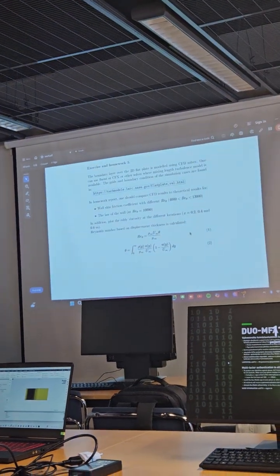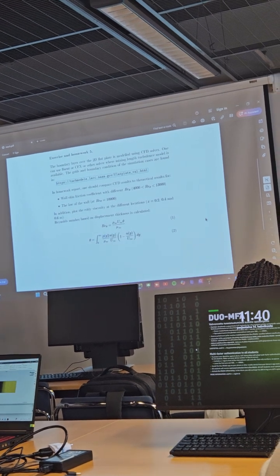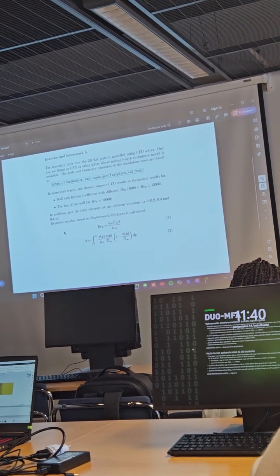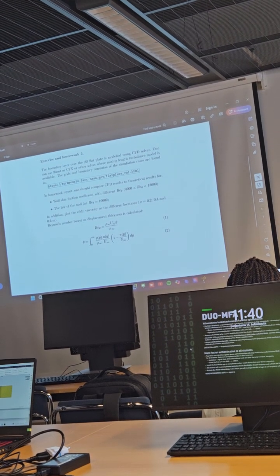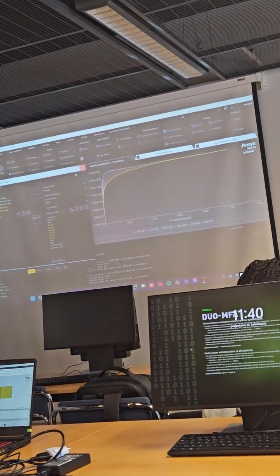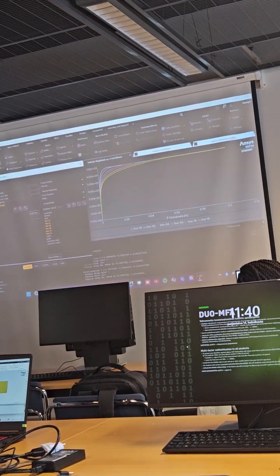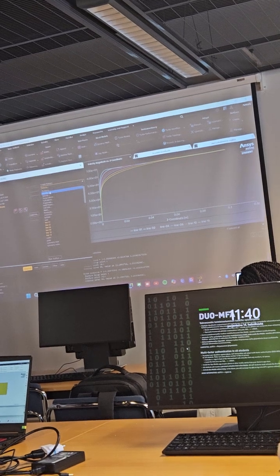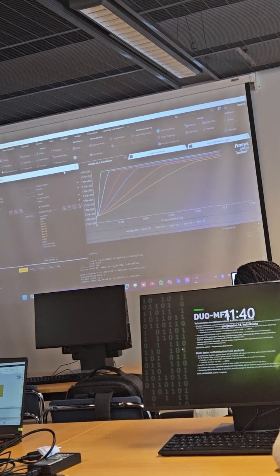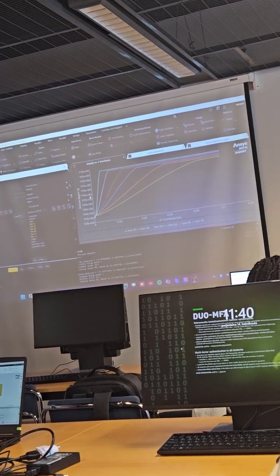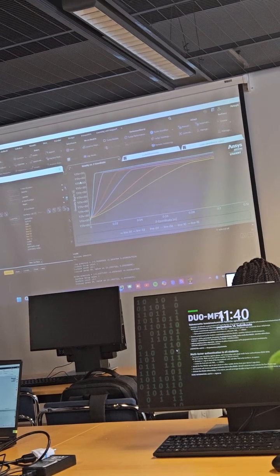So for post-processing, you would actually need also the density distribution, but again, this is incompressible flow. We use a constant value of density. And if you want to check what value of density is used here, I can use the select write to file, select density as a variable, save plot. So you can see that this is basically constant at 1.17. So the range is very small. So then you set it to 1.17.